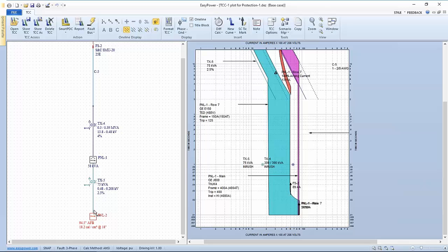Now in reality, testing has shown that arcing faults below 125 kVA at 240 volts won't last more than half a second, and so that's one way to at least artificially show a more realistic estimate of what these currents or energy will be. But in reality, why isn't something going on inside of this panel here? So let's go back and answer that question. The question I'm exploring is, why doesn't a protective device do something in this particular fault in that remote panel?